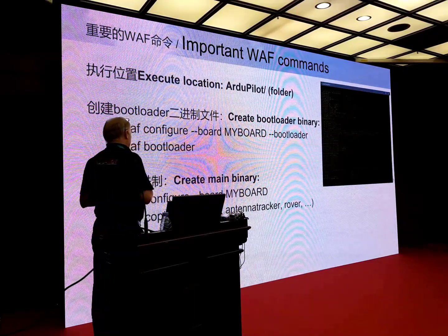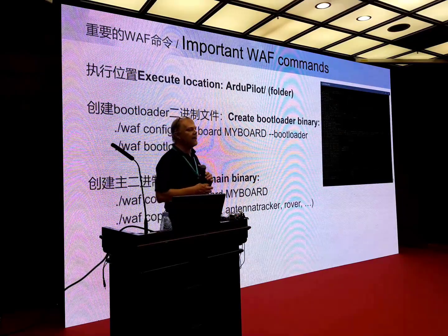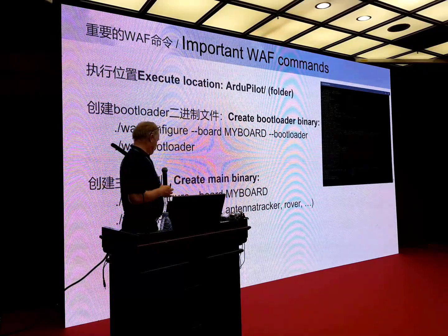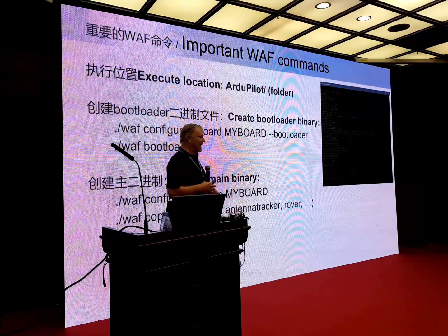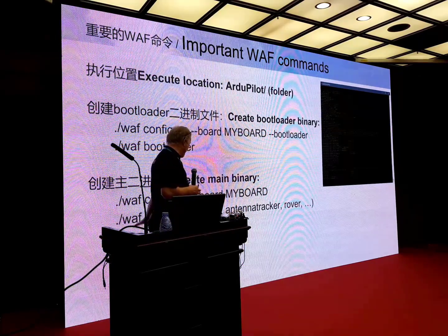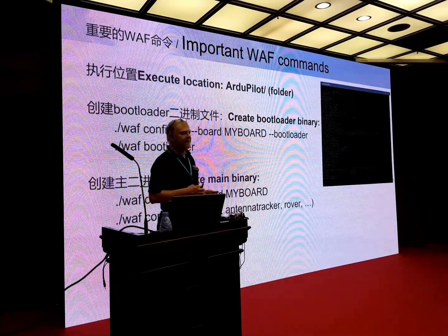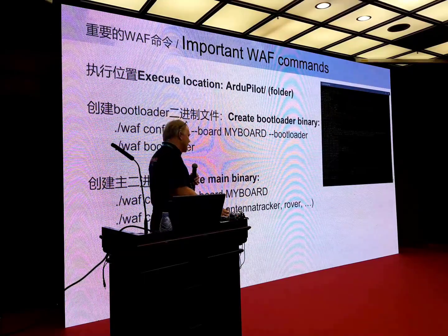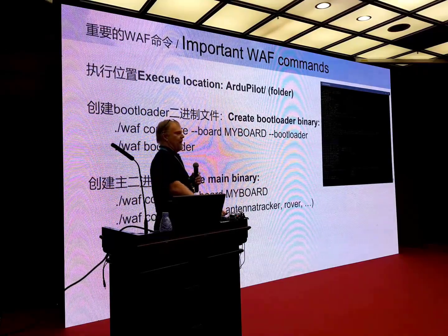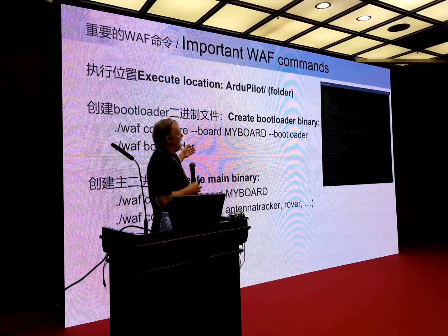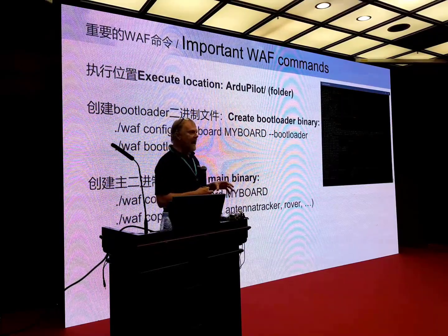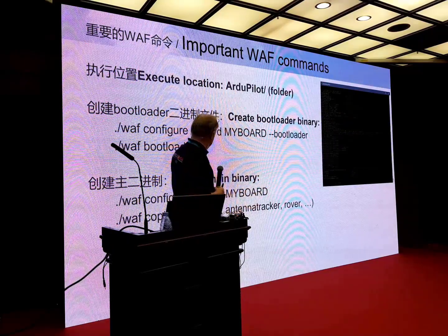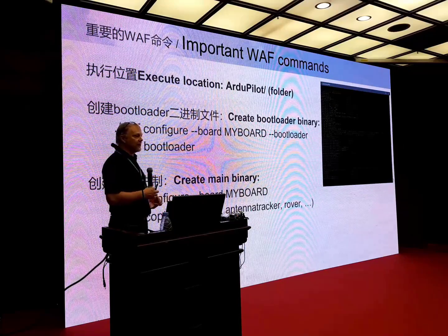Then when you are creating the final firmware, is it a copter or a plane or whatever, same again, you have waf configure --board and then your board name. The last one is, okay, which device I want to build. waf copter in this case. So it's pretty straightforward. There are many other commands and many other options you can put, but mostly when you're working on hardware that you have on your desk and you want to test that, okay, do we have correct connections and others, it's basically only these two commands that you are using.